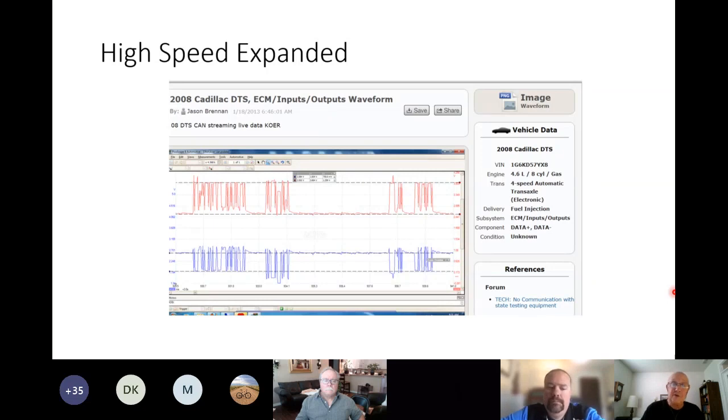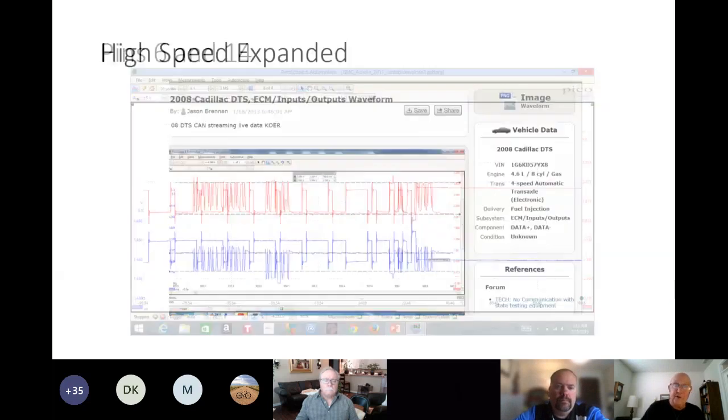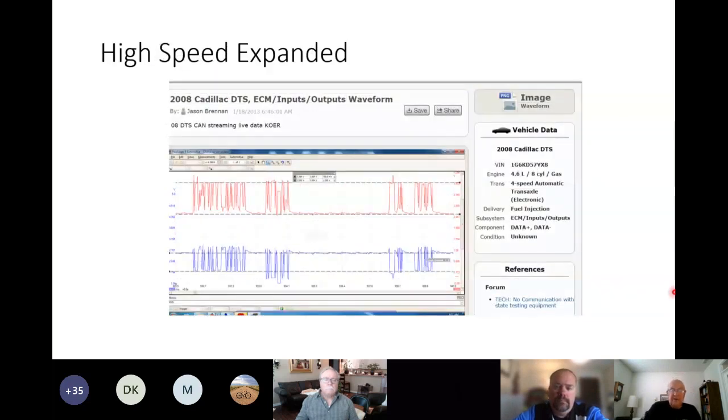After you unplug modules, you're going to turn the key on and see if you go back to a mirror image. If you go back to a mirror image and you started with this one, well, then it means, hey, that module I just disconnected was a bad one. In this particular case, Jason got lucky, and one of the first modules he unplugged was under the passenger seat, and the system cleaned up perfectly. He replaced that module, and everything was great.